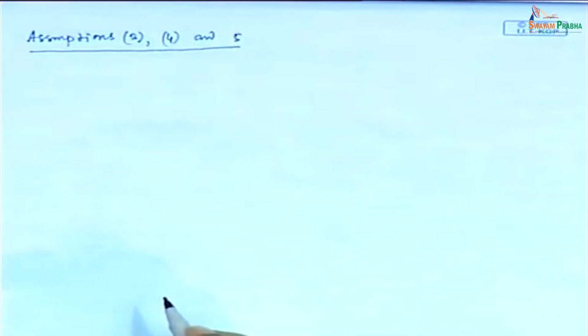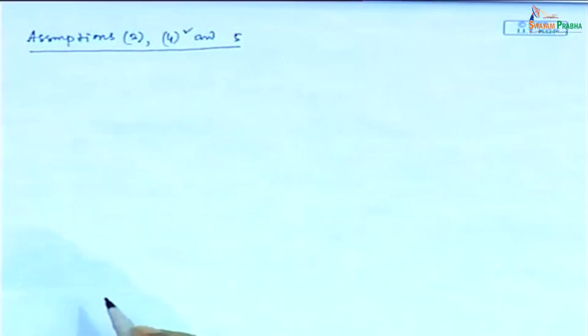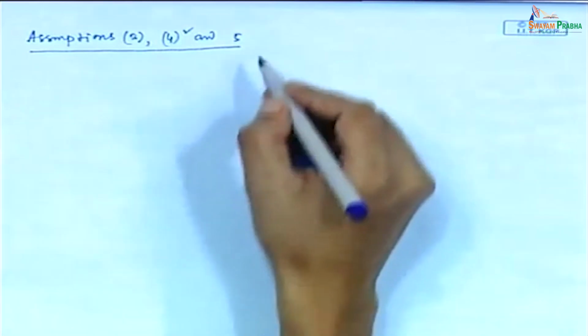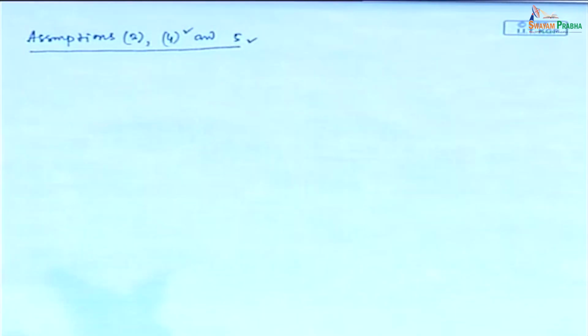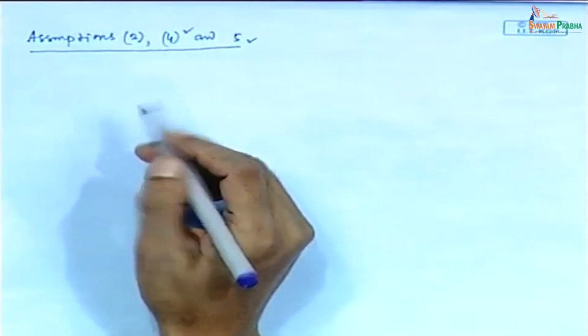The second assumption is that the column is perfectly insulated, so there is no heat loss. The fourth assumption is that vapor hold up is negligible on each tray. The fifth assumption is that if 1 mole of vapor condenses, at the same time 1 mole of liquid evaporates. Can we write, based on these three assumptions, that all the vapor flow rates are identical?